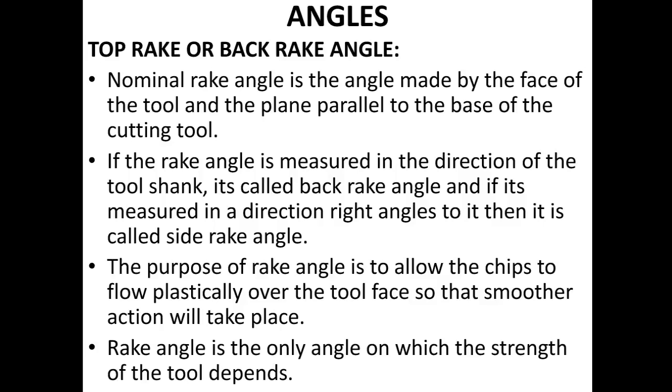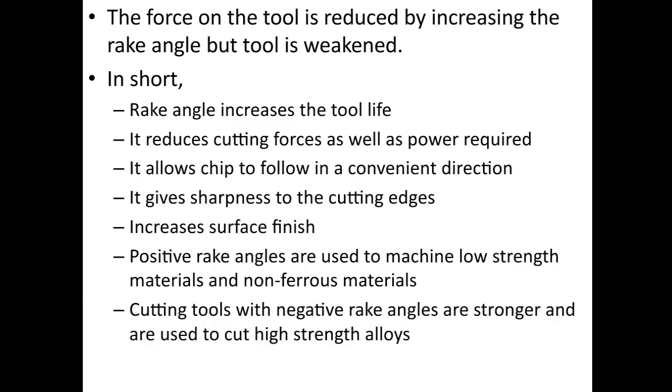Rake angle is the only angle on which the strength of the tool depends. The force on the tool is reduced by increasing the rake angle, but the tool is weakened. In short, rake angle increases tool life, it reduces cutting forces as well as the power required, it allows chips to flow in a convenient direction, it gives sharpness to the cutting edges, and increases surface finish.